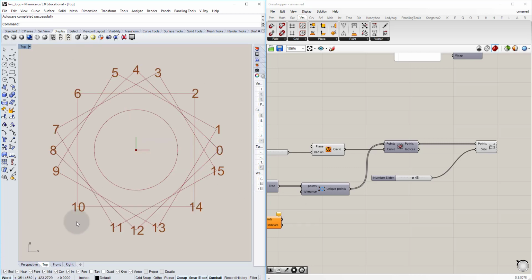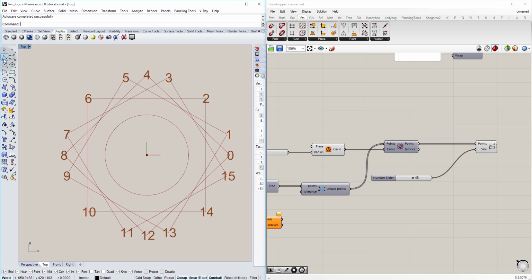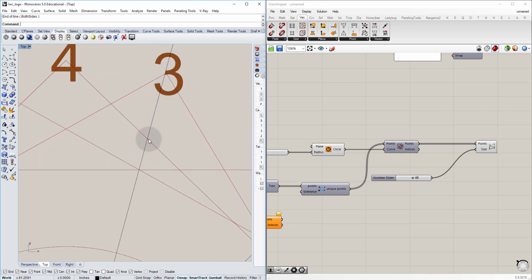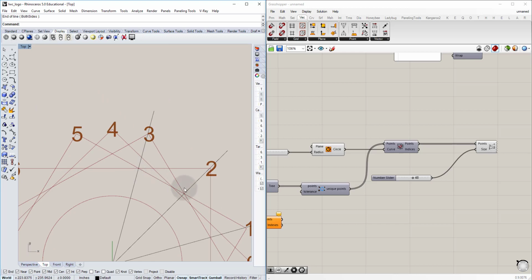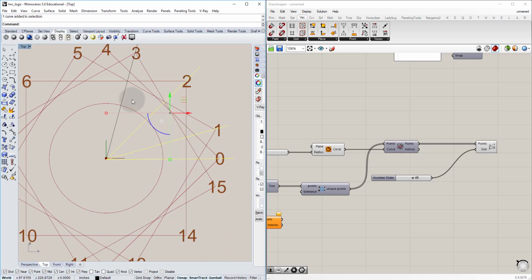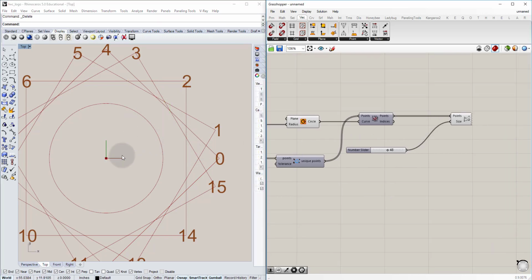What I want to do is, if I go in my top view, what I want is some type of surface that will cut all of the slabs in this direction, and then cut all the slabs along the 1, and then cut all the slabs along 2, and then 3, and then so on. Okay, because say I'm cutting along this corner, I'm also going to cut other slabs in this location and some other slabs down the middle or wherever that may fall, right? So how do I create these? This would be a really useful way, and one thing to do that I could try is just drawing these kind of lines, right? So let's start drawing lines that I just drew here, but using Grasshopper instead.